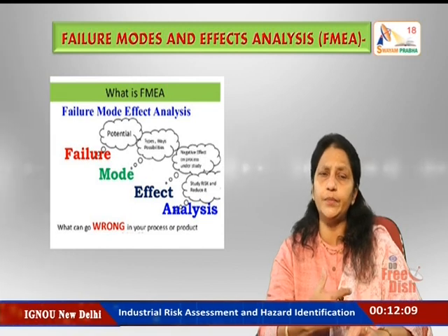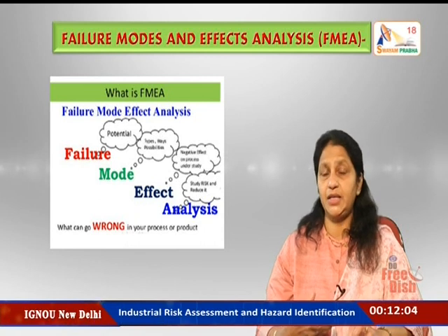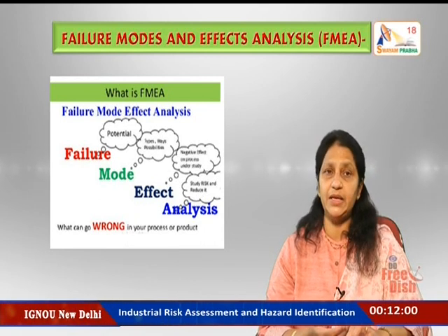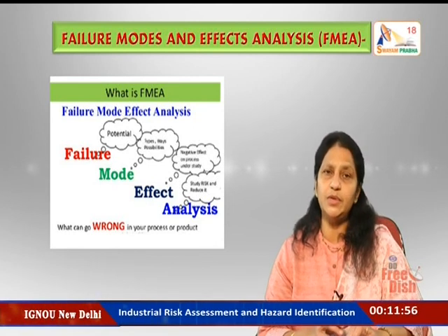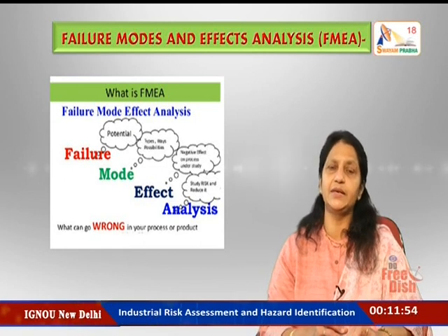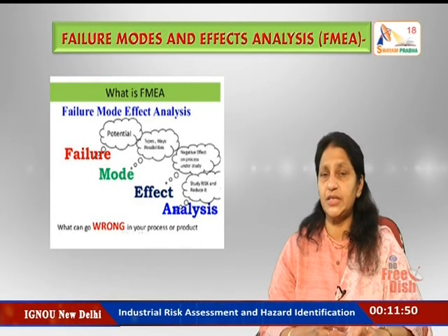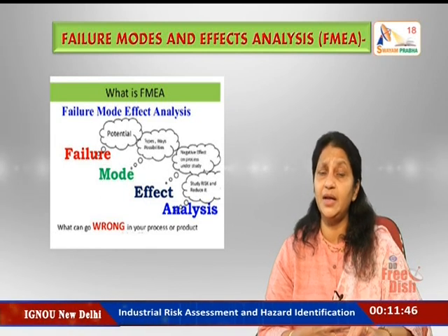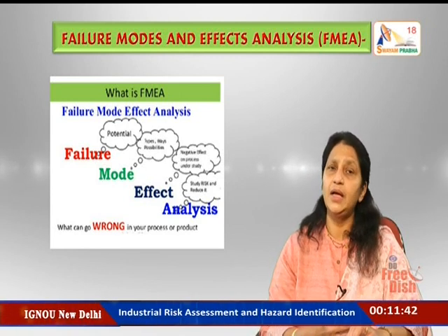To carry out the study, initially all items should be identified in the various systems or subsystems produced by the graphical breakdown of the process. All the possible failure modes of these items should be collated. The most likely failures caused by these modes should be identified, and their effects on the process evaluated.